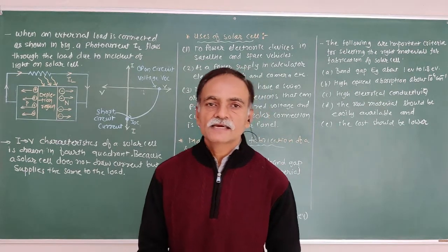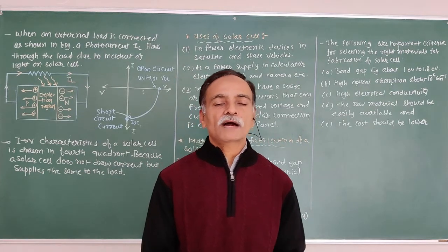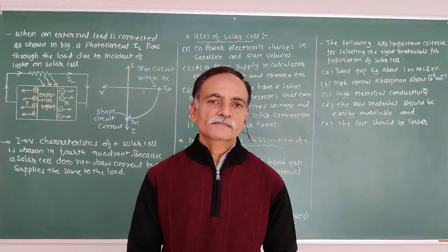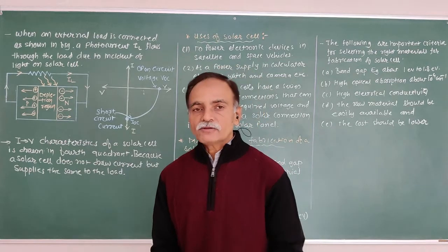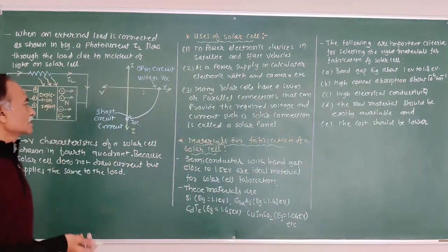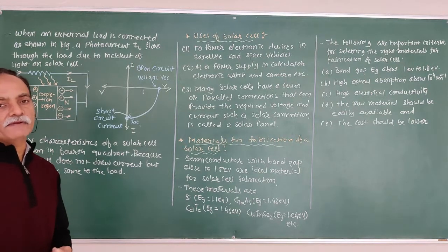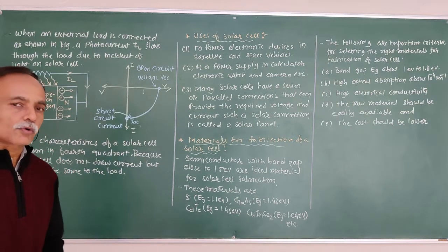As a result, the electron is swept towards the N side and the hole towards the p side. The electrons reaching the N region are collected by the top contact, and the holes moving towards the p side are collected by the bottom contact. Thus the EMF is generated between the top and bottom contact.